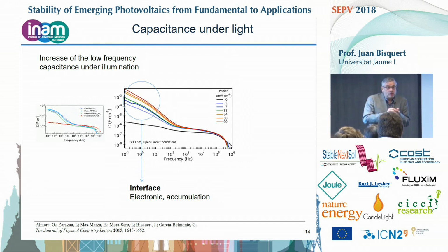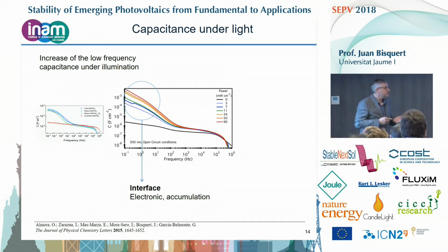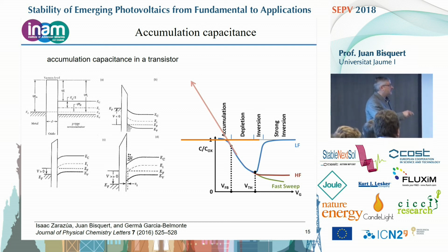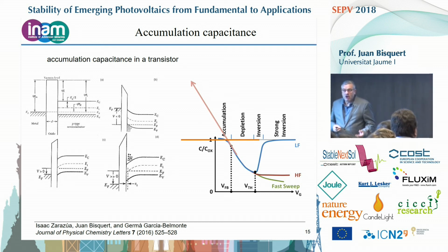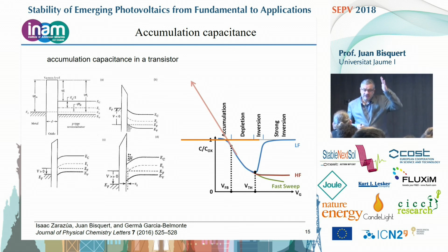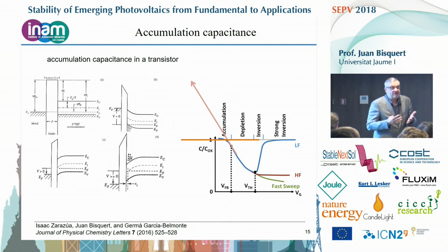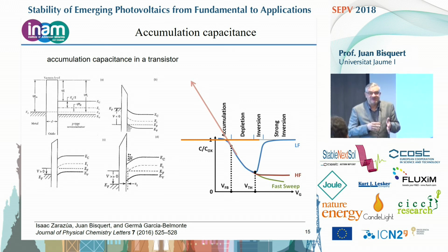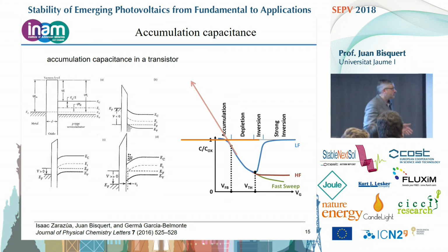But the electrons do not have size, they do not have limit. So it is well known in transistors, when you go into accumulation, like this case, putting the majority carrier Fermi level into the valence band, then your capacitance can go as big as you want. Of course, in a transistor, capacitance is limited by the series oxide, insulating layers.